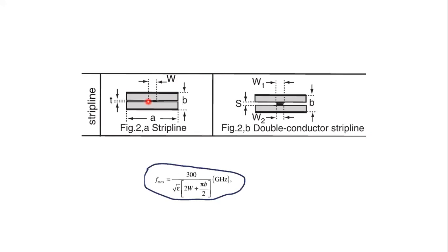But the same is not the case with the microstrip line, where this upper substrate is absent. You will have this ground plane and this top plate. Whatever circuitry we want to connect with the transmission line is all available on the top surface of the bottom dielectric material. Since there is no second dielectric material covering the structure, all the components are easily accessible. And if any fault occurs, it is easily traceable and we can troubleshoot it. That is an advantage.